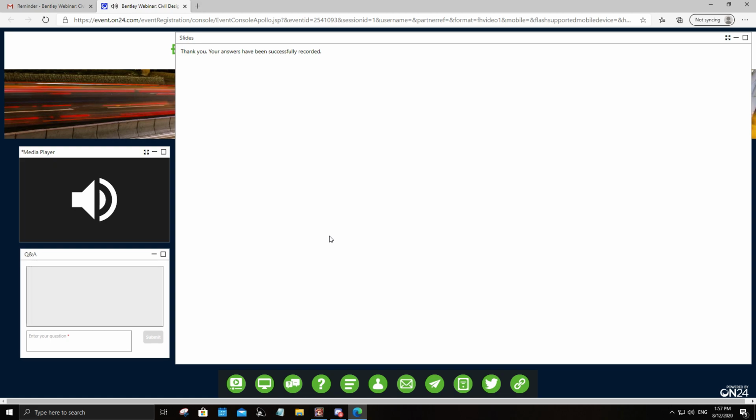Now we have another question from Mr. Christian of WSP. Can the software be used to generate average traffic flow to show more realistic traffic in an existing road? For OpenRoads ConceptStation, yes. There is already a built-in tool that will allow you to create a traffic simulation.